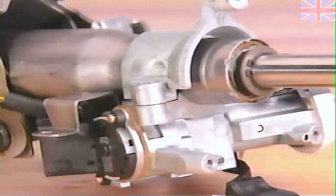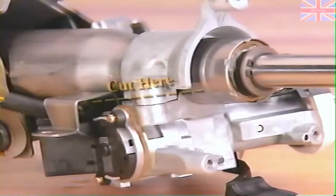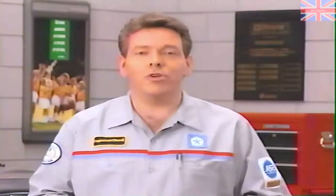To remove the steering lock cylinder from the steering column, you'll have to use a hacksaw to cut the special bolts through the steering lock bracket. Make your cut at the bracket, so when the pieces are removed, you can unscrew the remaining portion of the bolts from the steering lock cylinder. Use a new steering lock bracket and special bolts to install the steering lock cylinder onto the new steering column. After checking that the lock works properly, tighten the special bolts until the heads twist off.